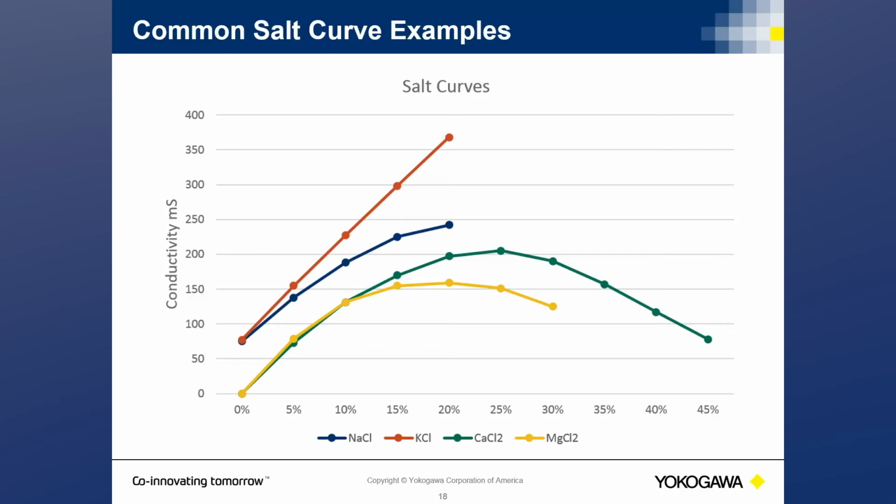The graph shown here is using our example of salt from the very beginning, brine solutions. It shows the correlation between the conductivity and concentration of 4 commonly used salts. These specific concentrations are obtained either by mixing a full-strength solution with water or by mixing a solid salt with water to achieve the desired percent concentration.